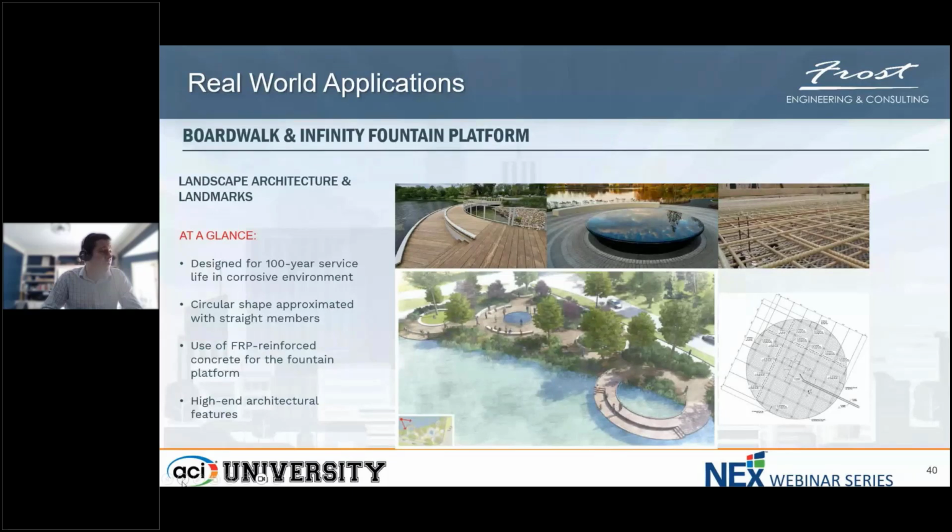The client, University of Notre Dame, sets a minimum of 100-year service life for effectively everything they build on campus. We asked at the project kickoff, when the schematic was assuming steel from the architect, if maintenance was going to continue dumping salt here. We have our first snowfall of the day here in South Bend, Indiana. We get a lot of snow and ice, and there's obviously a lot of concern about walking paths at the University of Notre Dame so students and faculty don't slip and get hurt. And the answer was yes, maintenance probably will be dumping salt directly on the structure. And if for some reason they decide not to do it directly on the structure, they're going to dump it right next to it and people will just track it on there.